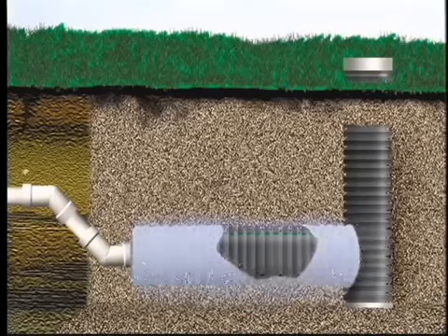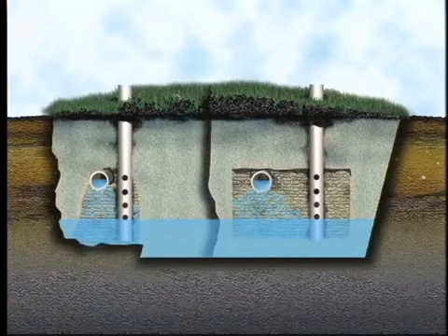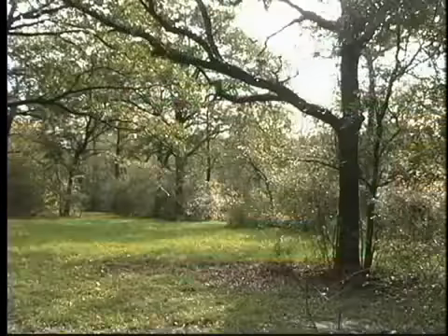These systems are designed based on rainfall and expected evapotranspiration rates. These beds can be either lined or unlined, depending on the permeability of the surrounding soil. Gravelly sands and karst soils require a liner. This can be made of natural clays, synthetic lining, or concrete. Unlined beds are used for impermeable soils like clay. Plant cover is essential for the proper function of these systems. Grasses and other plants must be well maintained for them to work properly.